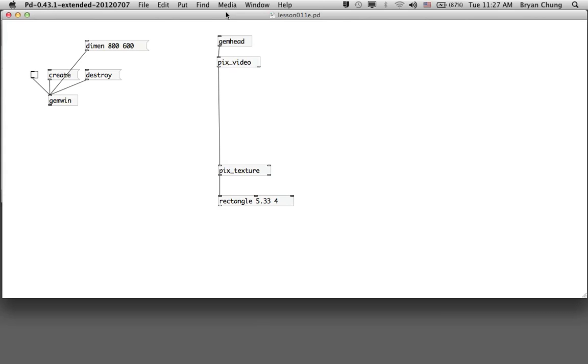This way, we are not comparing the current image with a pre-recorded background image. We'll try to make sense of the movement by comparing two consecutive images from the video camera. That means we compare the current frame with the previous frame, and if they are different, it indicates some sort of movement. Using the difference image, we'll try to make sense of the direction, position, and for example the size of the object which is moving in front of the camera.